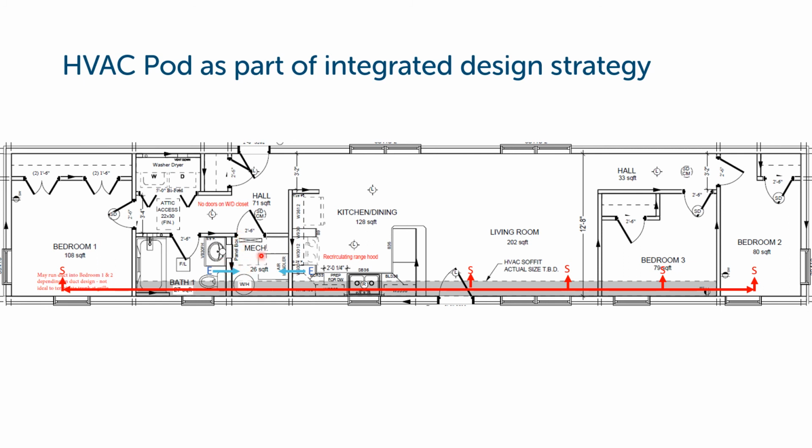Note the proximity between the mechanical closet and the bathroom and the kitchen, right? So we want dedicated stale air from the ERV. See this E here, this is exhaust. We get really good proximity to these two rooms, so the ducting is minimal for the dedicated return ducts.